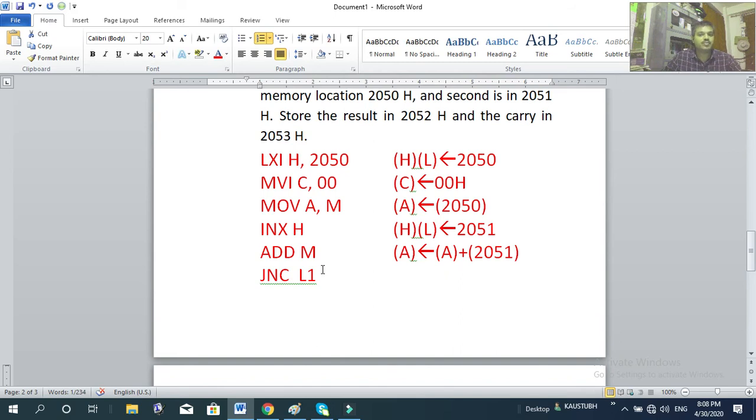Lower 4-bit: check whether the lower 4-bit sum is greater than 9, or whether the auxiliary flag is set or reset. If either of these or both are true, then it is invalid, and 6 is added to the lower 4-bit. If not, it remains as it is.